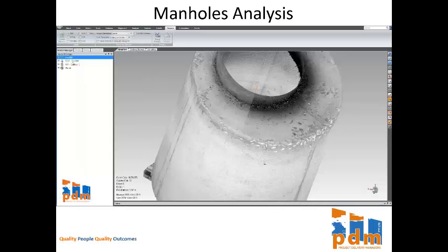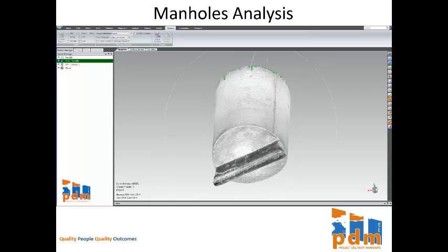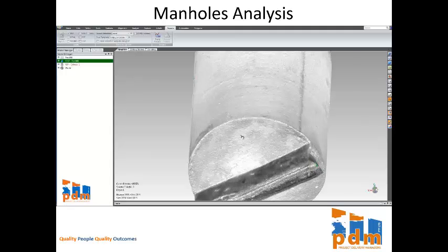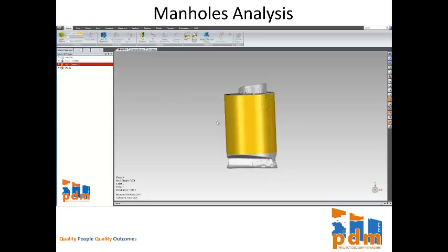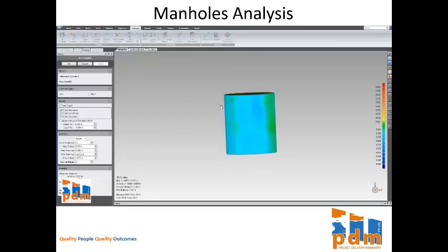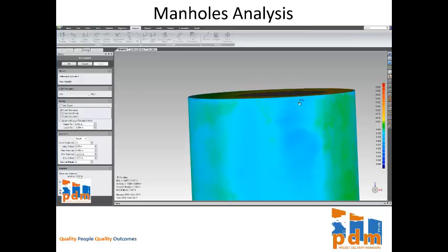The process for condition assessment involves creating a model of the design structure and comparing it to the 3D point cloud model. Comparison reports summarizing percentage deviations from design and cross-section analysis provide far greater condition information of assets than any other method. What can be seen here is the colorization of the differences.